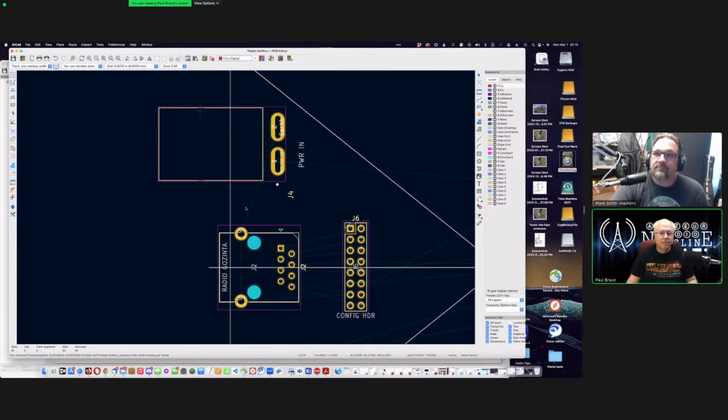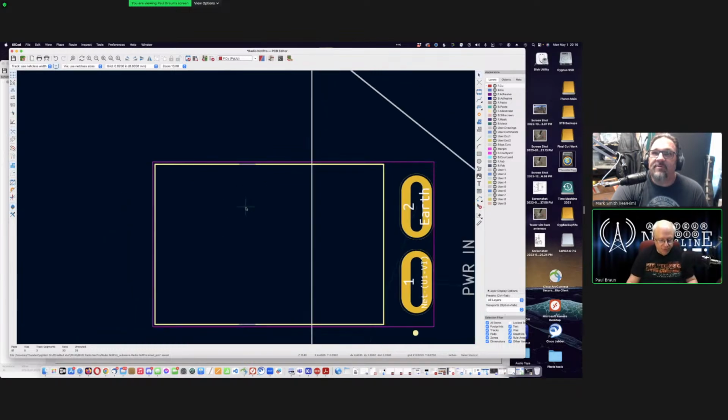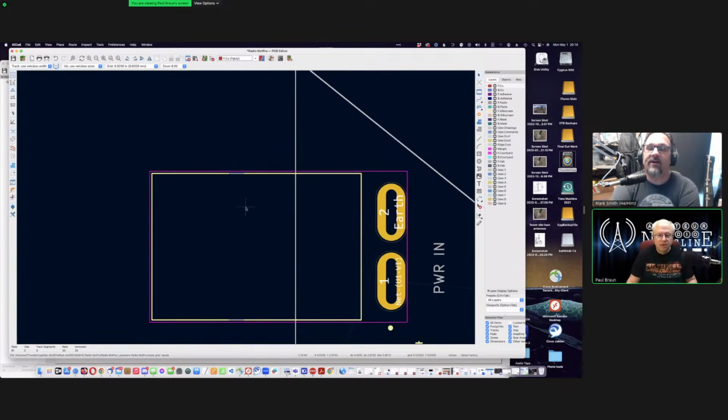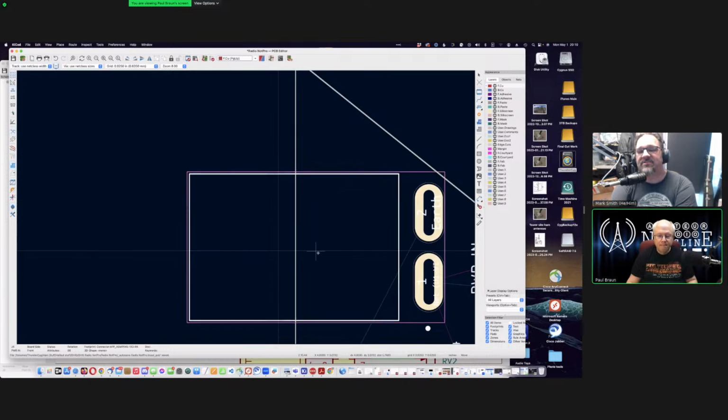Oh wait, you know what? Oh, look at that. There's a gray line here. Is that the notch? I bet the gray is the notch. Probably, yeah. So I would bring it back to the right a little bit farther. Of course, you can barely see the gray. Make sure the notch is at least a millimeter past the edge of the board. Technically 1.6 millimeters past the edge of the board.